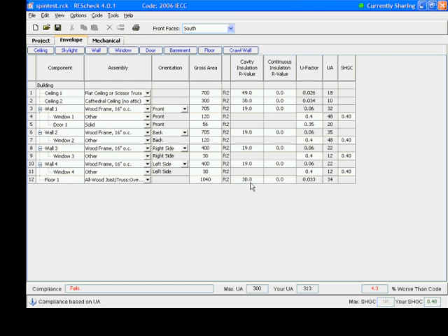And this is when I talk to you about different projects. Every project's different. You have to look at each one individually to really define what is going on, why one isn't meeting it, why one is. And on this one, I mentioned those hard limits. I mentioned the trade-offs. In certain climate zones, you can go up to this hard limit if you're trading off. But first, REScheck looks at that maximum U factor from the equivalent U factor table, and that's what it's using.